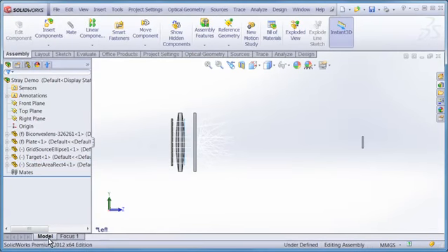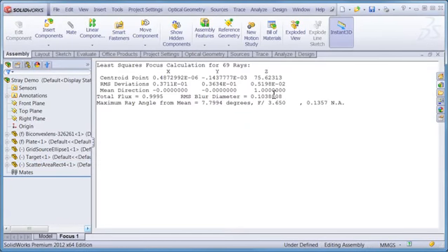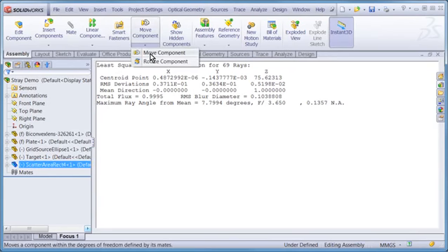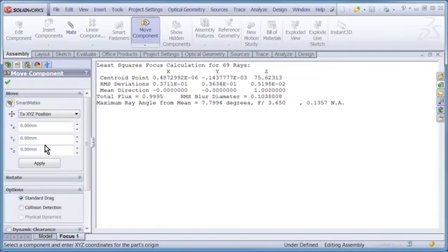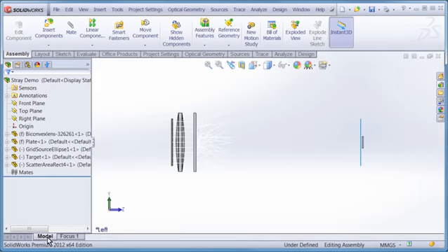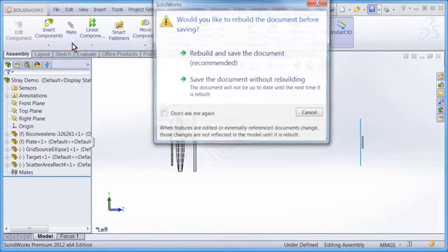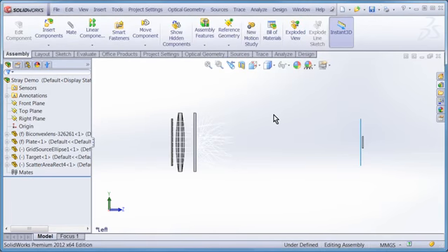So what I'm going to do is, if we remember back from our focus command previously, we want to put this again at about 75 millimeters away. So what I'll do is I will select my scatter area here, and from the Assembly tab, Move Components. And I'm not going to worry about the exact position, so let's just say 75. It's not going to really affect the angular subtents significantly, so let's just click on Apply, and OK. And now we can go back to our model view, and I think right now I'll save this file. And yes, let's rebuild it as well.